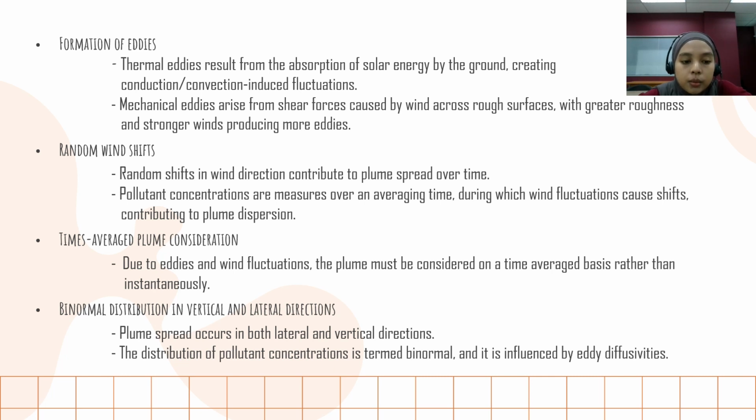Next is the binormal distribution in vertical and lateral direction. The plume spread occurs in both lateral and vertical direction, and the distribution of pollutant concentration is termed binormal and is influenced by the eddies distribution.